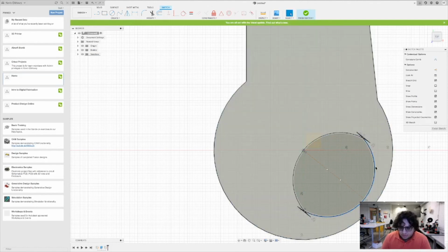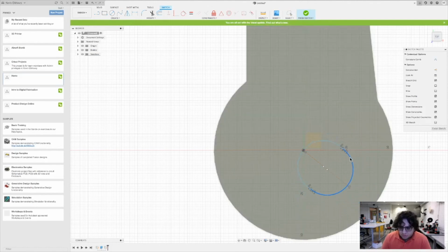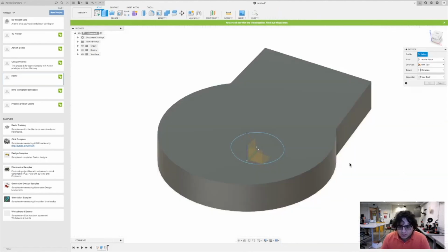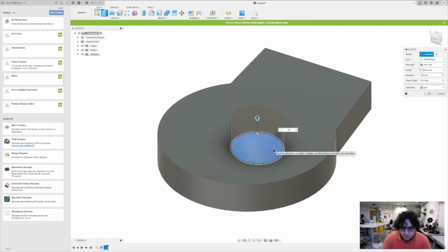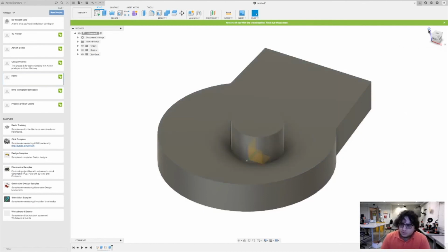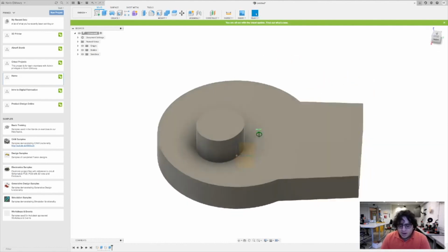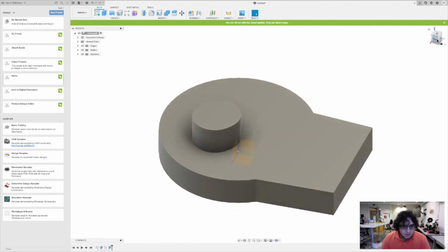All right. Now that we got this weird looking shape set up, I can simply use the extrude tool using E once again, select this one sketch, and say I want to pull it up by 20 millimeters again. And there we go. Now you're capable of making sketches on top of sketches to make more complex components.